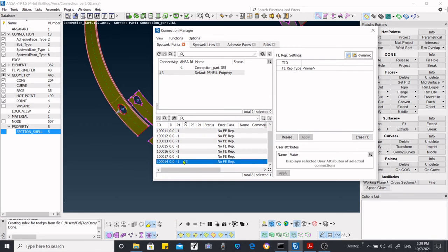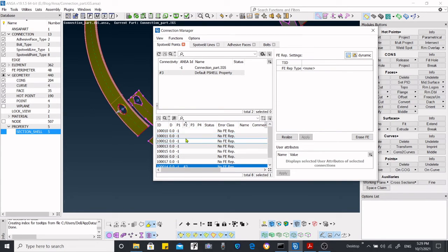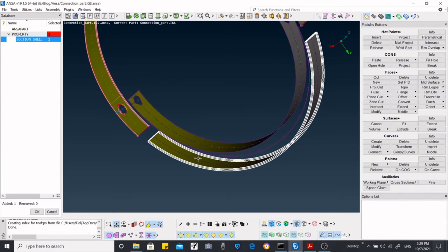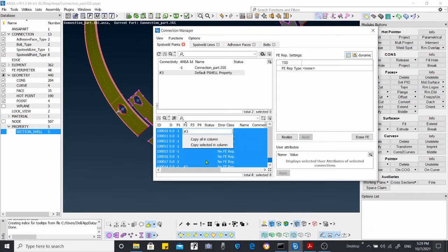It is selected, right? But it is not selected for every one of them. For that you have to press Ctrl A. Now go to this one. Again click F1, select this part, middle button, and then again press enter. Now we are seeing that it is selected for every one of them.